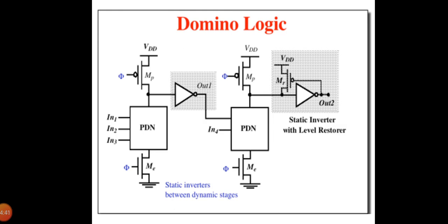So during this time, the second gate cannot pre-charge its output as the pull-down network is fighting the pre-charge device. Similarly, the third gate has to wait until the second gate pre-charges before it can start pre-charging. Therefore, the time taken to pre-charge the logic circuit is equal to its critical path. Another important negative is the extra power dissipation when both pull-up and pull-down networks are on. Therefore, it's a good practice to always utilize evaluation devices.